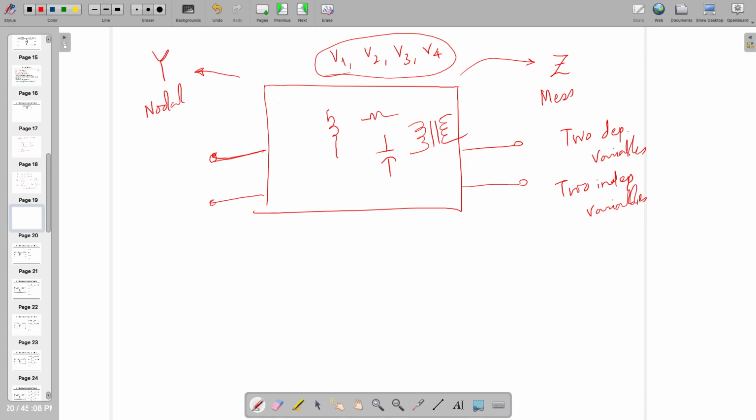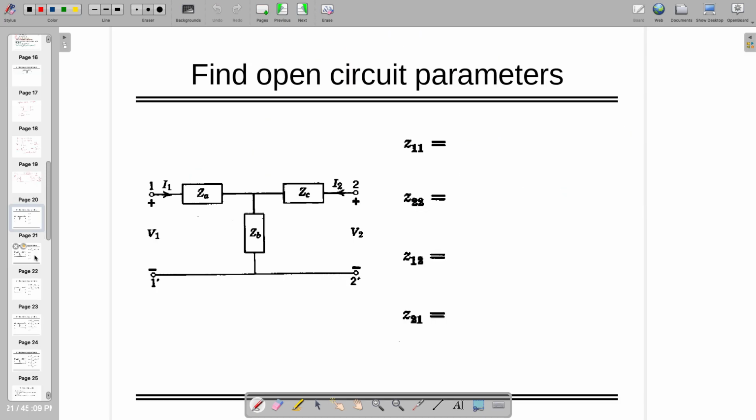Of course it's a modification of what we are doing here, but it's different analysis because we are only talking about two ports where we are interested in what is happening when I'm having following parameters V1, V2, I1, I2, and this circuit might be the black box. This analysis will be useful when you want to drive one circuit to another circuit, just to know that how much impedance will be offered at the input side or output side, or maybe in between if you are taking somewhere else. So this is how it goes, and that is what we are doing.